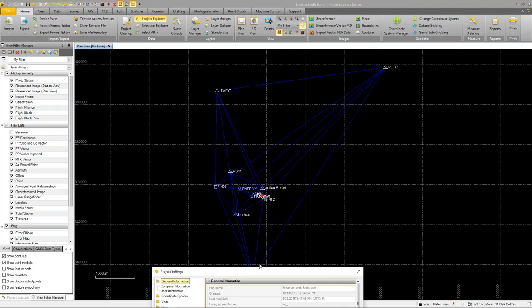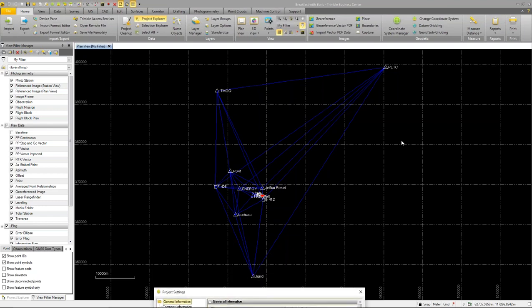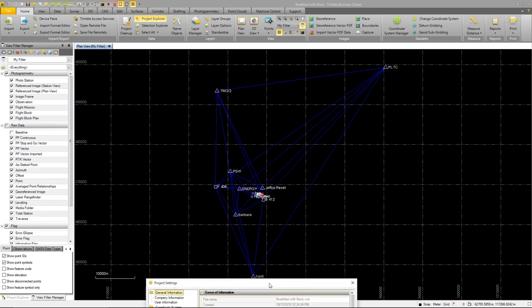From control points around our area, which happens to be near our office here in Colorado, there are some federal agency control points that can be used for horizontal control for this network, and the network has a lot of points in it that are right around our office area. So we have a mixture of horizontal control or 3D GNSS derived points, lat, longs, and heights, and we have a lot of points that have benchmark only or elevation only control quality coordinates.